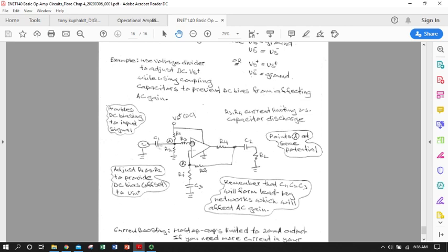So this shows an op-amp in that same situation where we have a coupling capacitor on the input, so we don't have any DC offsets coming in that we didn't want, and that we're also not interfering necessarily with our supply and our AC input. And we have the same thing here on a feedback network. If there was some AC signal coming out, which since it's our input we hope there is, it's going to be effectively decoupled from any kind of DC signals coming in from ground.